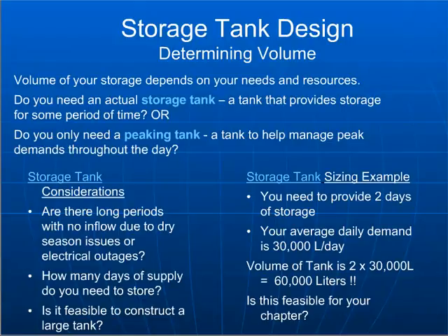So again, make sure that if it's a storage tank that you need, then that's how you're basing your decisions, using that type of information to figure out what the volume needs to be. Now the other type of tank, which is probably much more common in typical community scale water systems, is a peaking tank. This is basically a tank that's going to allow you to manage all of those peak demands that are going to occur during the day.